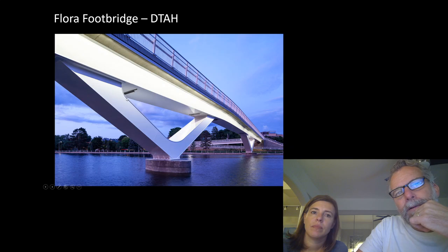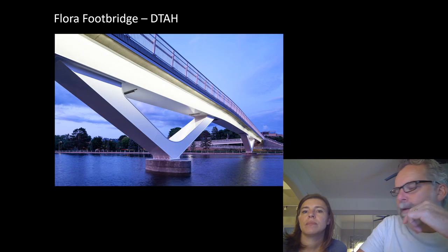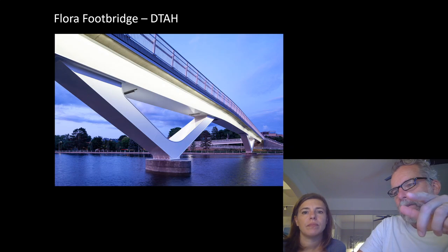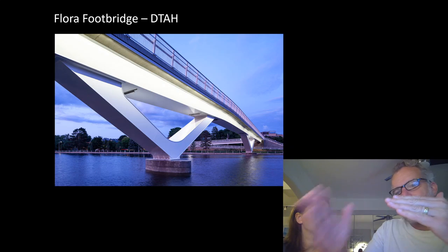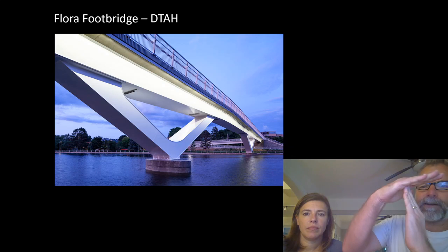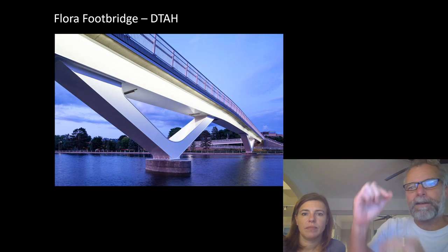This is a very typical condition here. You can see that the flange overhangs the web by a small amount. This is so that you can weld them with a fillet weld. A fillet weld is very effective when you've got 2 things coming in at 90 degrees to each other. You fill the little gap with a fillet.